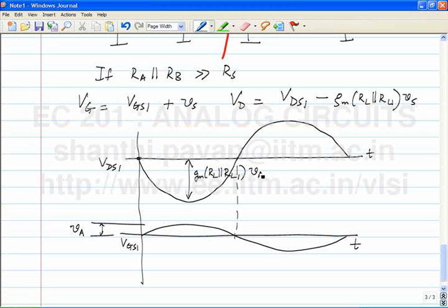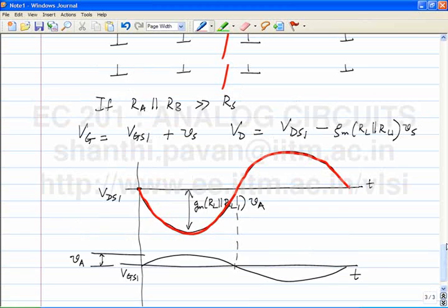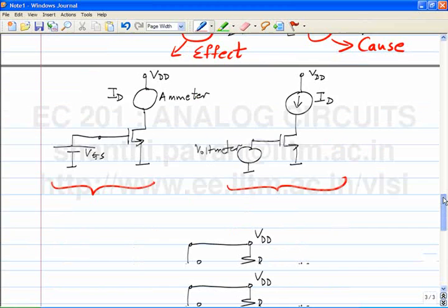So when do you think you will get incremental gain? What all conditions need to be satisfied to get incremental gain? Small signal, okay. What else? When a MOS transistor is giving you gain, it is operating in the saturation region. Okay. So now if I go on cranking up Va more and more and more, this waveform here is the absolute voltage at the drain. Oh, please note, what is the absolute voltage at the output here across RL1?